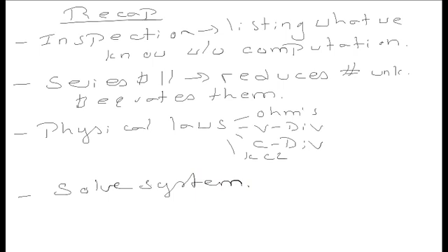I've already said this, but at all times our goal was to reduce the number of unknowns and get the smallest system, which means the fewest unknowns per equation that we can. We use nodal analysis because nodal is a general technique, much more so than mesh analysis. In general, whenever you're setting up your system of equations, nodal should be your starting point.